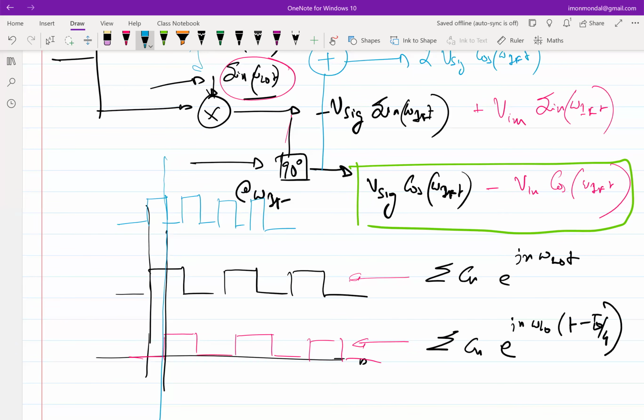Pardon? Yeah, it's basically an XOR operation, I agree. I'm not saying it is not done, but when you do an XOR operation, essentially you are doing a combinational operation. You can do an XOR, it will work. But sometimes you are beholden to the delays of the XOR network also. If you are working at very high frequency, you'll have to take care of something additional instead of using only an XOR. The XOR is going to give an additional delay. It doesn't come for free, right? Then you have to tweak for that additional delay.